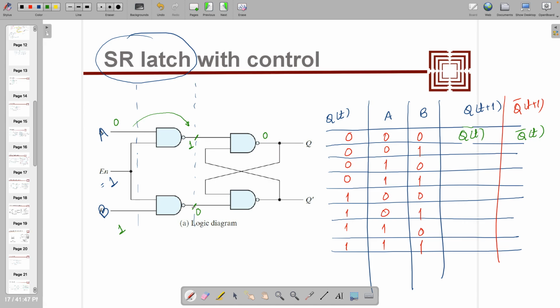Right? After 1 nanosecond, because this processing was happening in parallel, the input of this latch part is actually 1 and 0. If this is 1 and this is 0, Q bar will become 1 after 2 nanoseconds, right? This 1 is going over here, 1 and 1 will become 0, right? 0 is coming here, so it's 1, right?